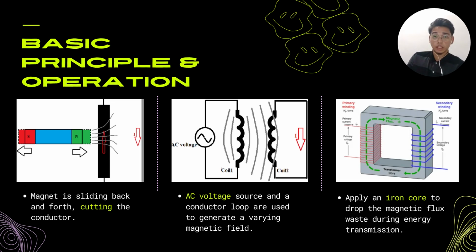So next, as we can see in the third figure, both coils are hanging in the air. So the medium for the magnetic environment is the air. The air has greater resistance in comparison with metal in the case of a magnetic field. So if we employ a metal core as a medium for the electromagnetic network, then we can obtain electromagnetic induction more effectively.